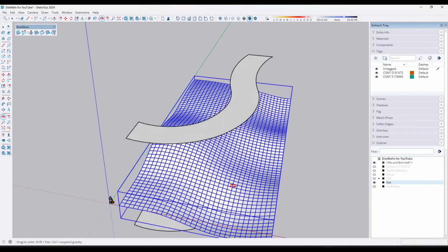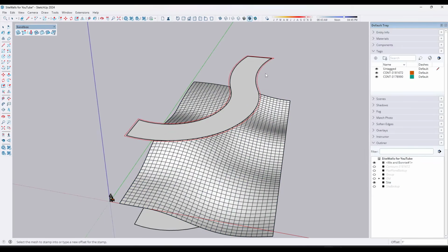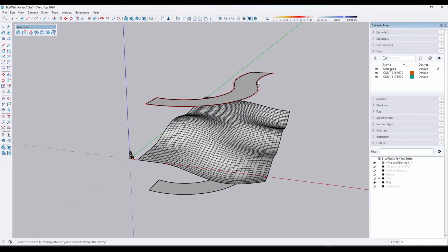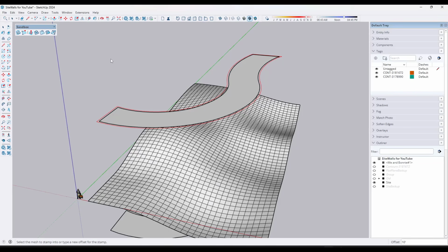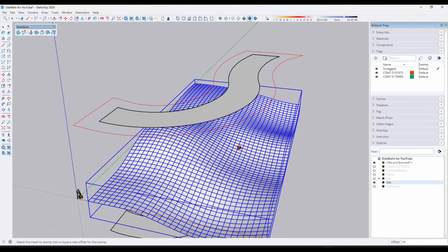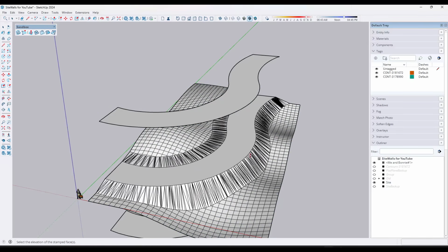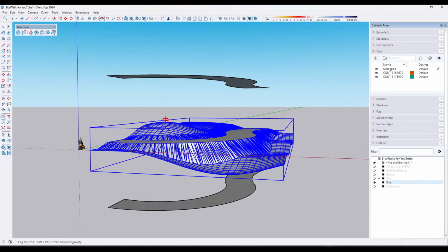Now in this situation, remember that we want to create a road that has a retaining wall on either side of it. So in this situation, we don't want to have a big slope in here, but remember that there is a function in here for offset. And with a function like offset, what I can do is I can type in a value of 10 feet. Notice how you get this red line in here. For whatever reason, that line doesn't update unless you restart the tool. But when I typed in a value of 10 feet, notice how what this would do is this would kind of give me a slope away from my road like this. Now, there are times that that can be valuable, but this isn't one of the times because we want to keep the terrain close to the road.